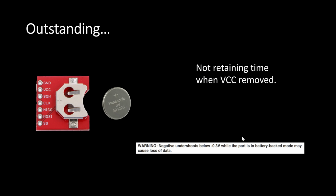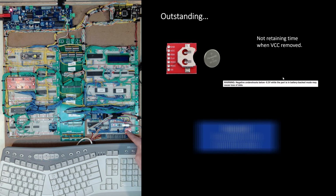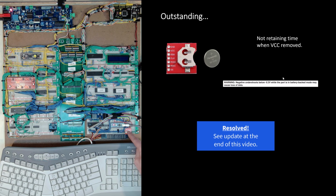Now I have one outstanding issue, which is I'm not sure what the cause is yet. I do have a new battery in here, and what I'm finding is that it's not retaining. If I remove power from VCC on this PCB, it does not retain the values that it should be retaining. So I have to see what's going on there. I don't know the cause of that yet. They do mention in the data sheet that an undershoot of anything more than negative 0.3 volts can cause data loss. I don't think that should be happening, but I didn't see anything else that would give me some clue of why this isn't actually retaining.